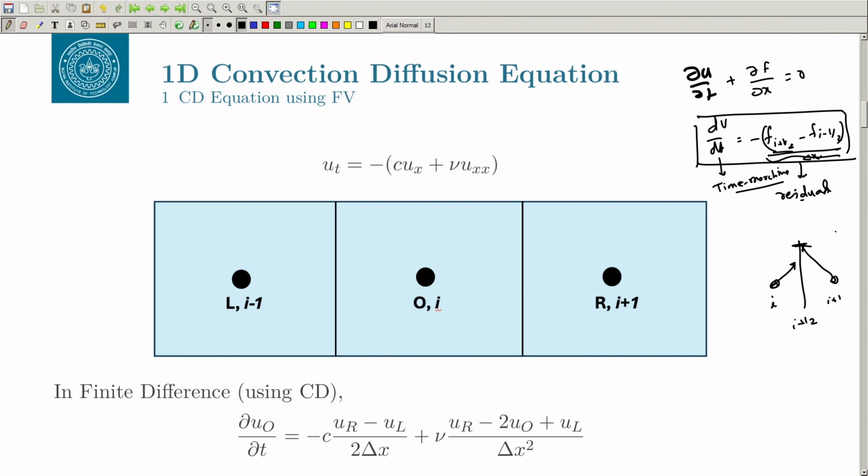That is where the flux schemes come in, whether you use the Lax-Friedrichs scheme or the Roe scheme or the van Leer scheme or any scheme like HLLC, AUSM. What they do is take the reconstructed values from the left and right across any cell and give you the unique flux. There are certain properties on how the flux should be, so that the code does not diverge, and good flux schemes retain those properties. Of course, while trying to do that, you may also have some dissipation in the scheme. This is similar to what we have discussed in finite difference.